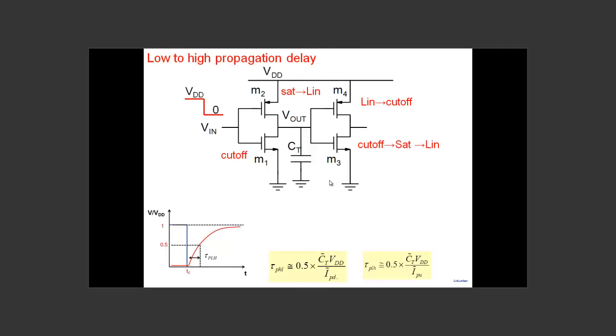And the capacitors, to calculate them is a little bit involved, but at least we can see conceptually what the capacitors are. So in the black font, I've shown here the capacitors associated with my inverter, the switching of that particular inverter that I'm interested in. So you can see here there are capacitors. If I look at this particular node, the capacitors come from this transistor M1 and from M2.